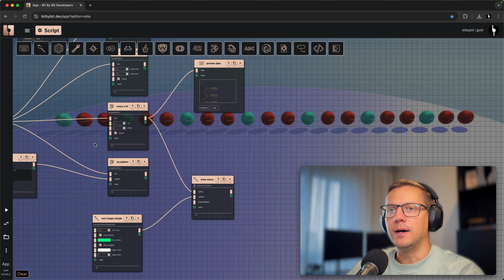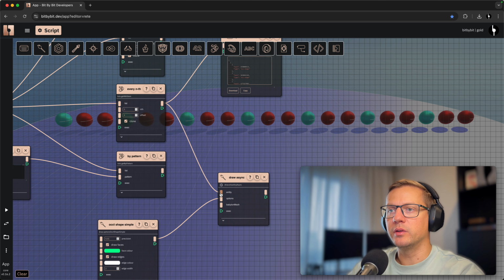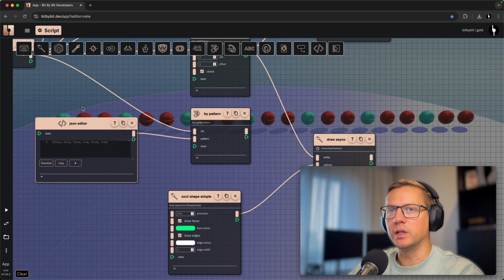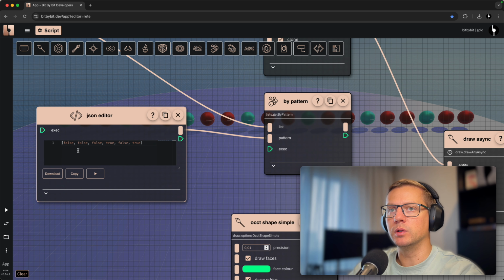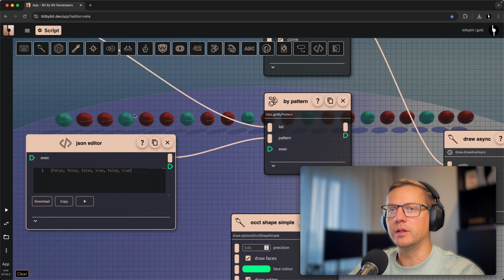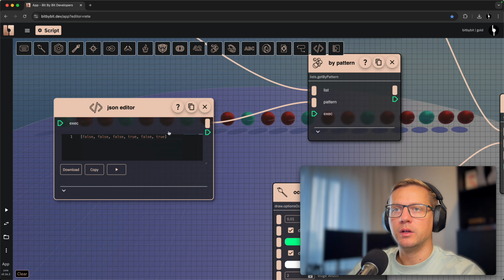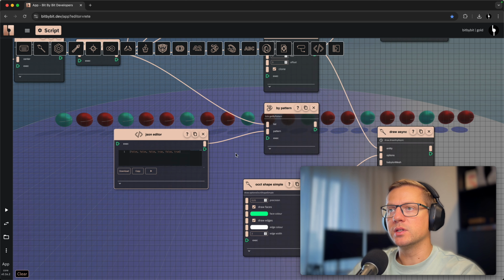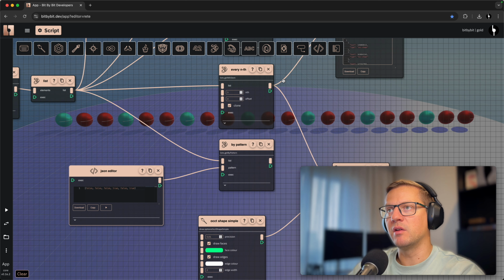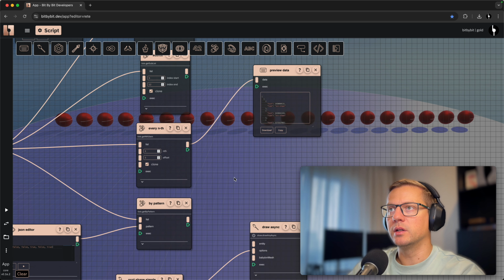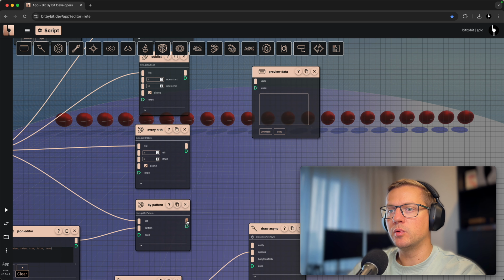So this offset is really useful quite often, which depending on the list that you're working with can be a lifesaver. Okay, another component that is really useful is to create a pattern of booleans which will indicate which item will be required and returned. So I've created some complicated pattern here. You see it starts with false, false, false, and you have then true, false, true. So this is something that you couldn't do with this every nth component, and we do need to use the pattern then. So let's look at the output of this component as well.